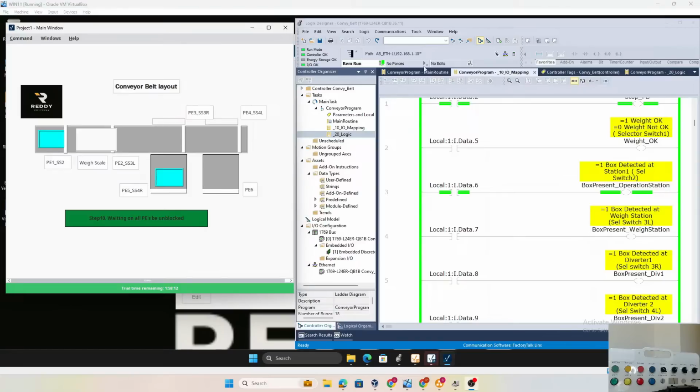As you can see here on the screen, I'll be using Ignition for presenting the HMI, and on the right side you see the finished PLC program for the conveyor belt application we talked about in the previous video. We'll be using a COMPACT LOGIX PLC here with a firmware revision 36.011. We'll guide you through each step in offline mode, ensuring you have solid fundamentals for automation projects.